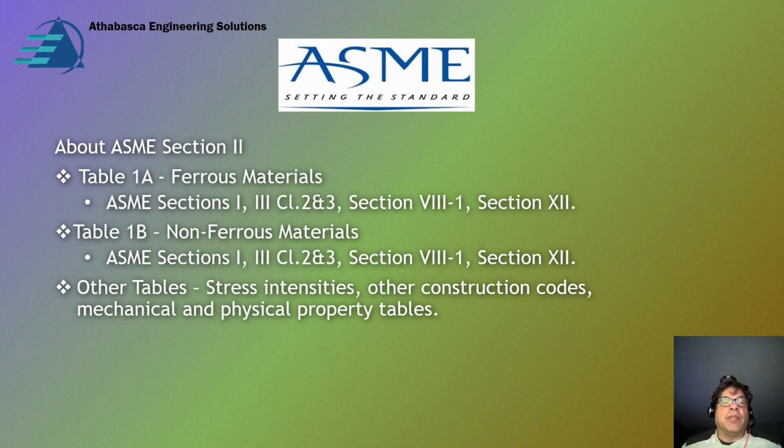We're into ASME Section 2. Table 1A is ferrous materials, and we're referring to Part D here. Basically you have to be careful about which code you're using. So there are tables specific to, say, Sections 1, 3, Class 2 and 3, and Section 8, Division 1, which is the one we're going to be looking at today, and Section 12. But there are other tables, and the same thing with the non-ferrous materials.